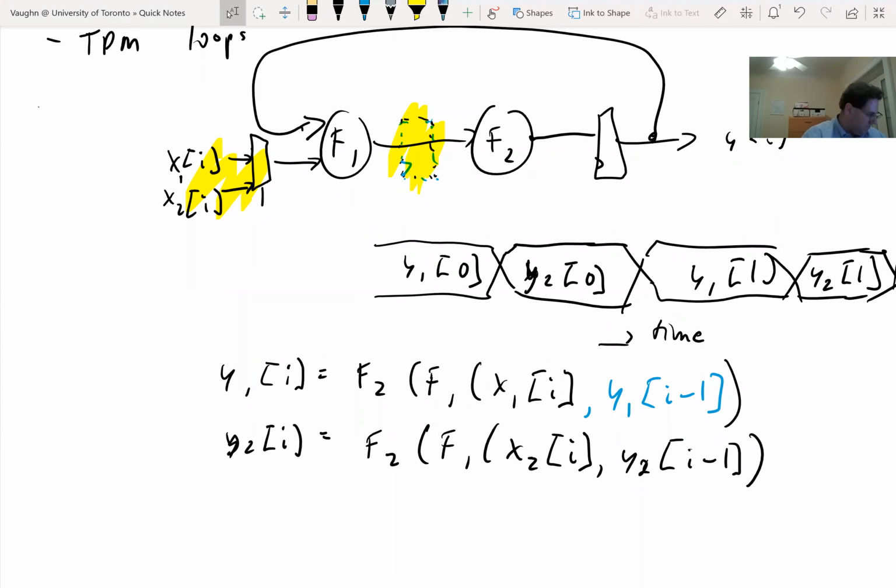Hopefully that's clear. This is a spot where I usually confuse people. Does this make sense? By interleaving 2 data streams, I can now increase the latency of this loop by 1. So I can double it from 1 cycle to 2 cycles, and everything is correct because I interleaved 2 data streams. In fact, when I interleaved 2 data streams, I had to increase the latency of the loop to 2, otherwise it wouldn't work. But doing those 2 things together, they essentially cancel each other out. I wind up computing 2 different streams of data, and they're both correct.